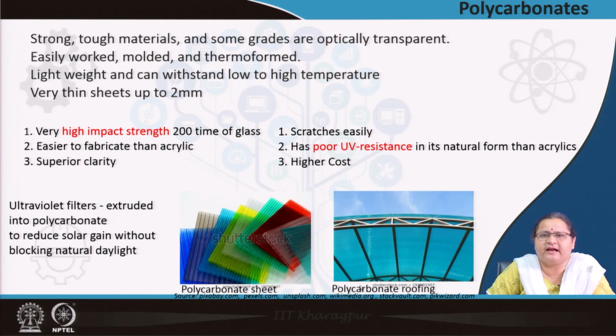Now, you can improve the ultraviolet radiation resistance of this particular polycarbonate sheet by adding some filler materials into it, and that is the additives that can actually make it more durable to outdoor uses, and hence polycarbonate sheet similar to acrylics have large application in outdoor environment, say cycle shades, say outdoor or temporary shoppings, temporary even bus stops, bus shelters.